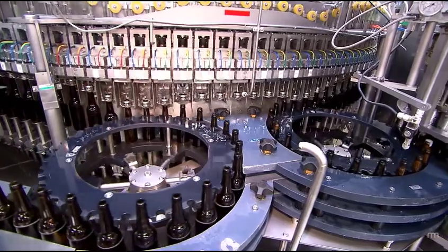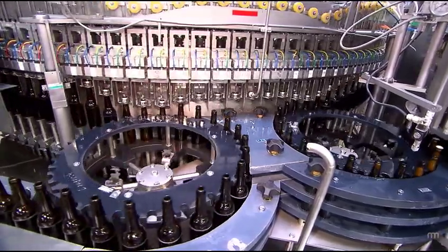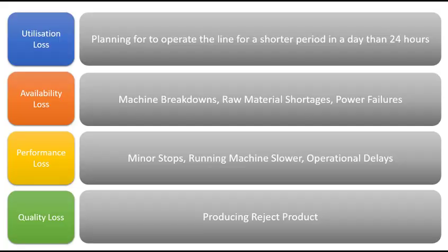With this option, you can double your output of 2,638 units to about 5,200 at the current OEE of 53%. But you pay dearly in terms of the extra labor hours and increased overtime rates. The best resort is to increase OEE and minimize utilization, such that utilization is the next resort once OEE is maximized. Then, once both OEE and utilization have been maximized, you can go and justify to the shareholders capex to buy the bigger and faster machine.